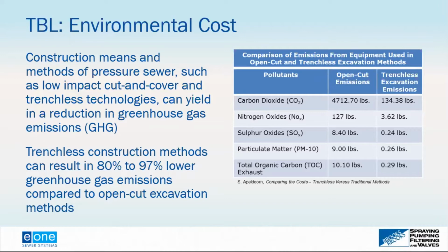As I mentioned earlier, with pressure sewer systems, you can use low impact cut and cover or trenchless technologies. There was this report, and I don't have a date on the footnote, but I believe it was in the early 2000s. This report came out where there was an evaluation comparing the cost of trenchless versus traditional excavation methods. And this was not done for a sewer system. This was pipeline excavation in general. So gas, water, sewer, cable, anything that involved a trench. That's what they were evaluating in this process.